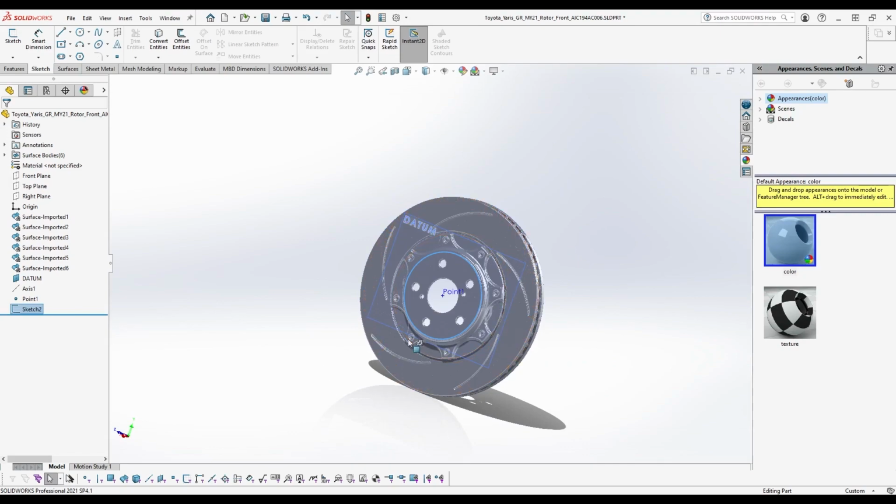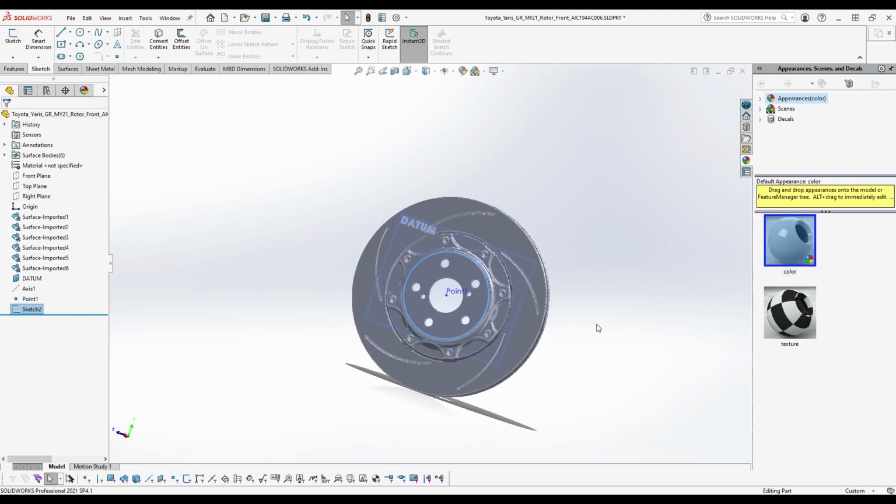And you can pick a plane that is perpendicular to the first plane at a point. So say you've got a front chassis rail, you might want to make the datum plane off the front end. And then you know that the chassis rail is meant to be perpendicular to that, but they obviously have a level of manufacturing tolerance in them. So you'll say, well, I want to make a plane that's perpendicular to the front one, and then pick the side of the chassis. So there are plenty of ways to do it. Just make sure you're always referencing off of that datum plane.